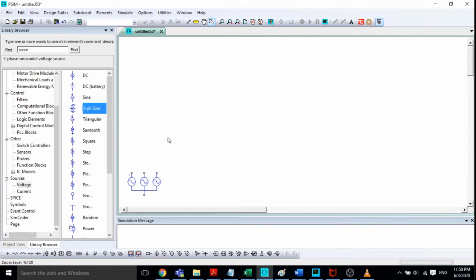The second component we're going to be using is the resistors. This one you can get from the speed bar here. So let me grab the resistor. I'm going to put this quite far so I have more space to put all the cables and instruments here. So let's put this one here, this one about here, and this one about here. So now we have the 3 resistors, and we need to add all the instruments.